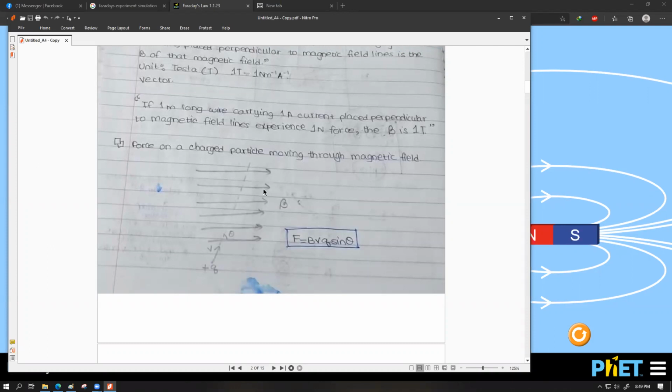I'll show you why. Everyone, try to make the famous left hand rule gesture in your left hand. First, identify your left hand, which is on your left side, and then make the famous left hand rule gesture with your 3 fingers. If you have done this already, you should remember that your thumb represents the force direction, your index finger represents the magnetic field direction, or magnetic field lines direction to be more exact, and your middle finger represents the current. What you need to understand is that the charged particle flow movement, or the velocity of the charged particle, is a direct representation of the current flow.